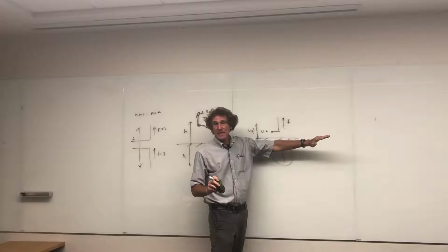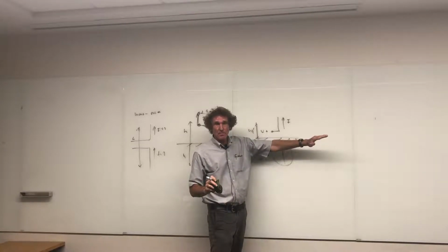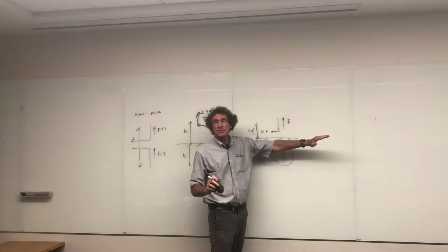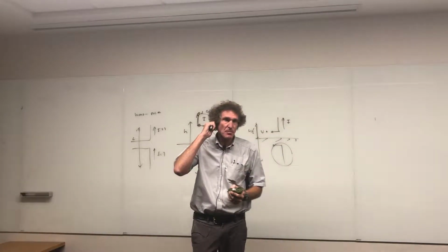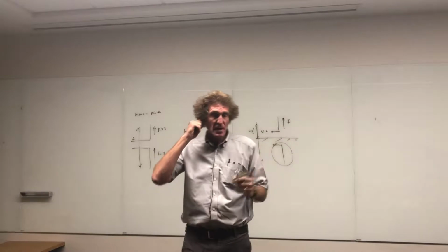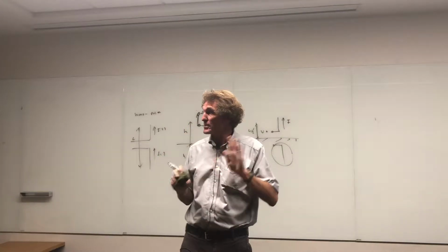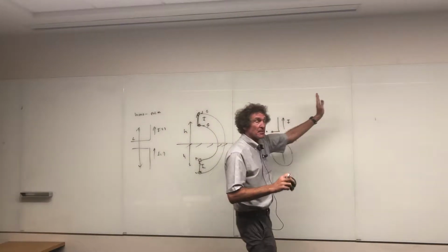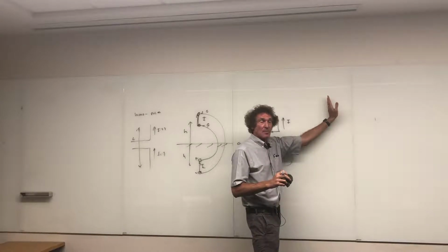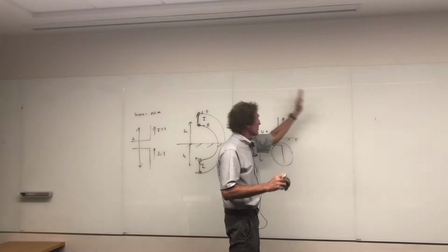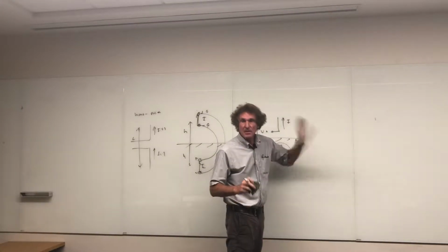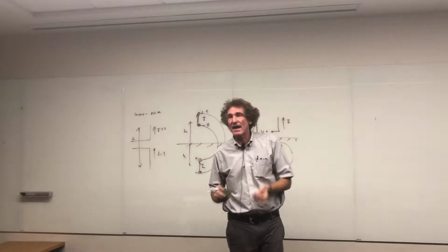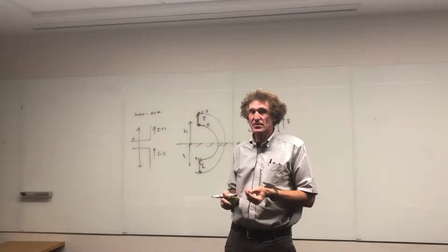The directivity or the gain double to that of a monopole, and the radiation resistance goes down by half. And that should make logical sense. Radiation resistance is proportional to the power, right? Think about it. If the power is identical in terms of the E field up here as it would be for a dipole, then the power density out here would be the same. Same radiated power would be in the upper hemisphere. Do you all agree with me? But there's nothing radiated in the lower hemisphere, so exactly 1/2 less power, 50% less.